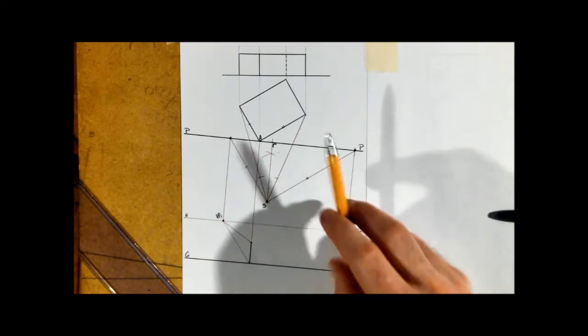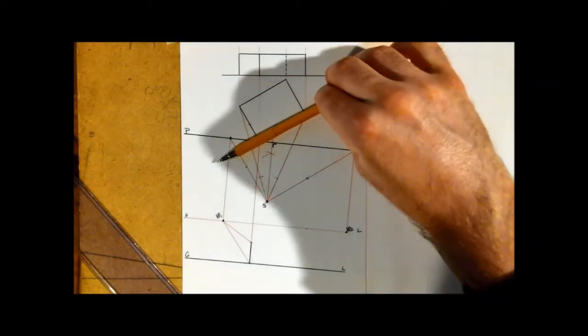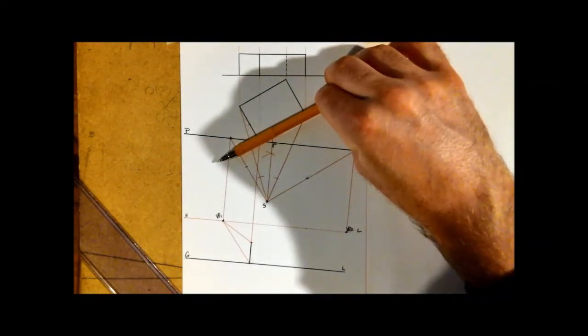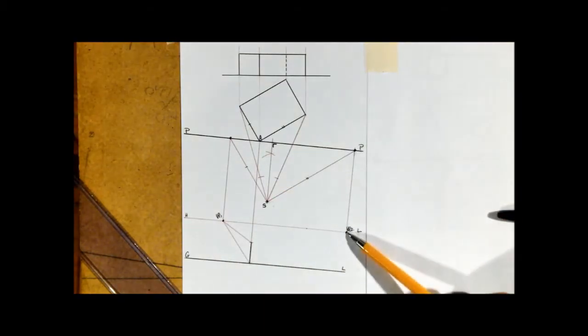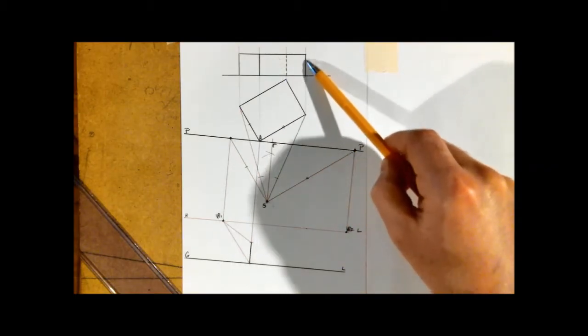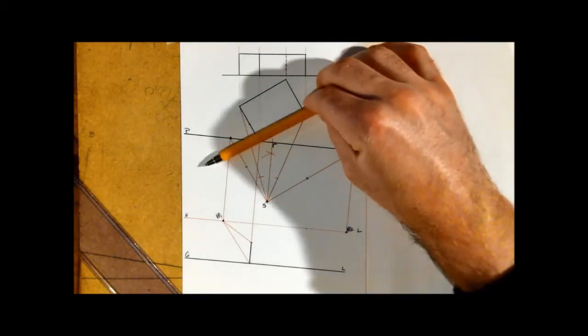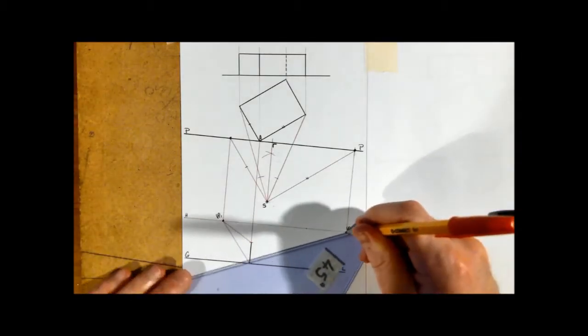Okay, now once again we have another face here. The exact same thing, just follow the opposite way. Any lines that are going in this direction are going to vanish over in this direction here, which is in line with VP2. So any faces that are going this way, and in this case it's this face up here, are going to vanish over to VP2. So once again, I can vanish them over to VP2.